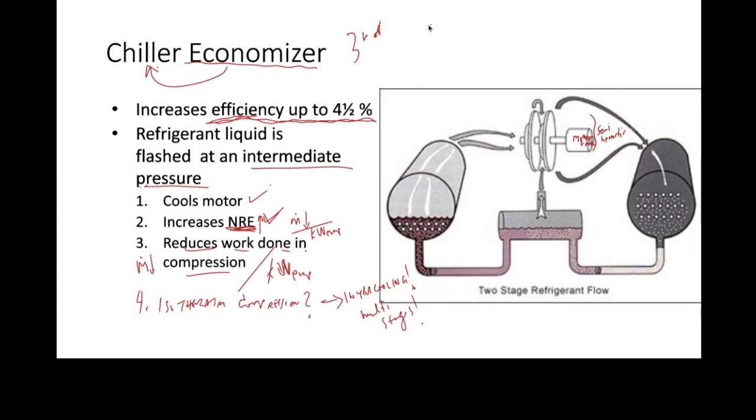Well, what you know about intercoolers is this. I've got a reciprocating machine here with a low pressure cylinder on the left and a high pressure cylinder on the right. And then what we're going to do is take the gas and put it through an air-cooled or water-cooled cooler, and we're going to put it into the HP cylinder.